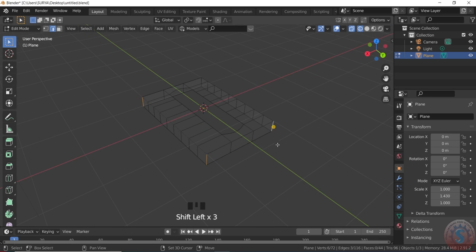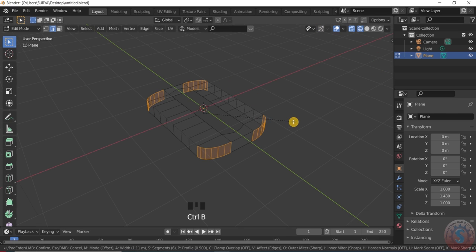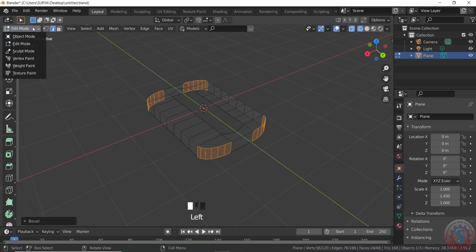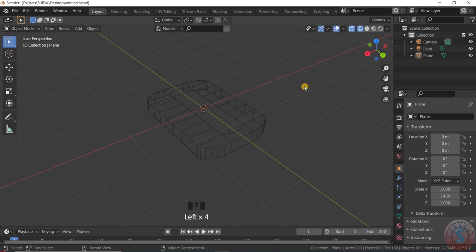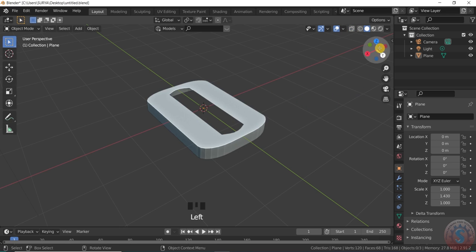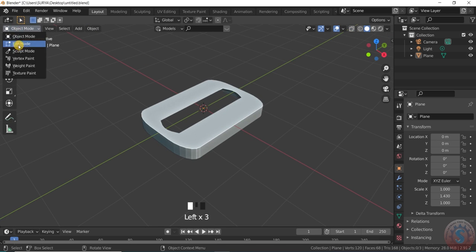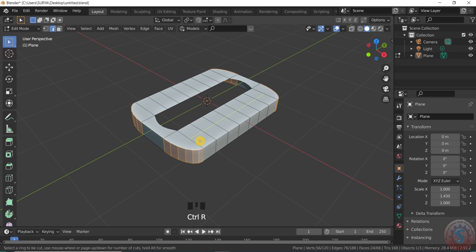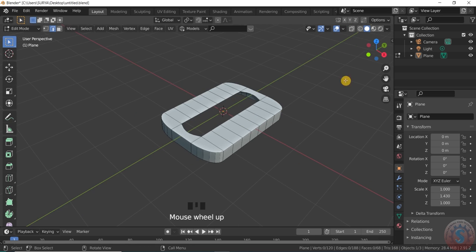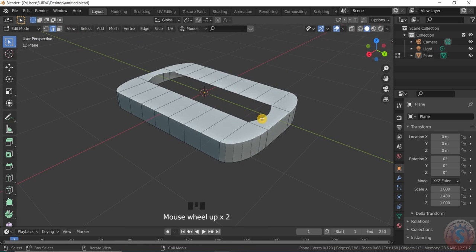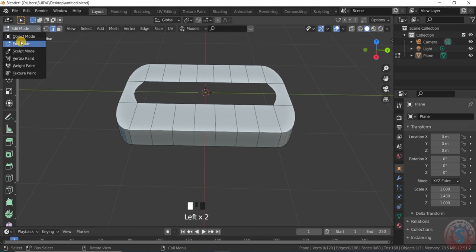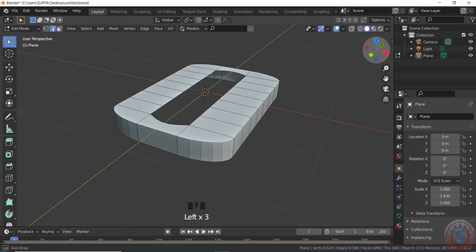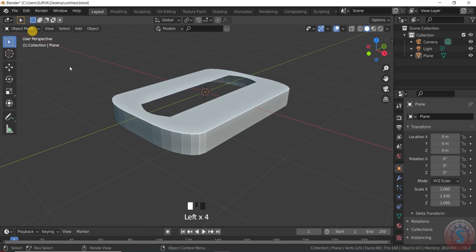By using Control B, I bevel the object with 6 segments, go into the edit mode and give the segments as 6, then go into the object mode and switch to solid mode. Then the solid object is created like this. Go into the edit mode. You can observe the loop cut is giving some edges, but the loop cut is not forming on some of them. To fix this, I am using the knife edge topology or connect vertex path, creating the knife edge topology in edge select only.